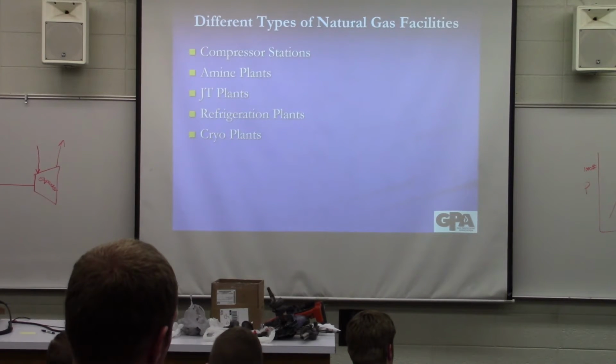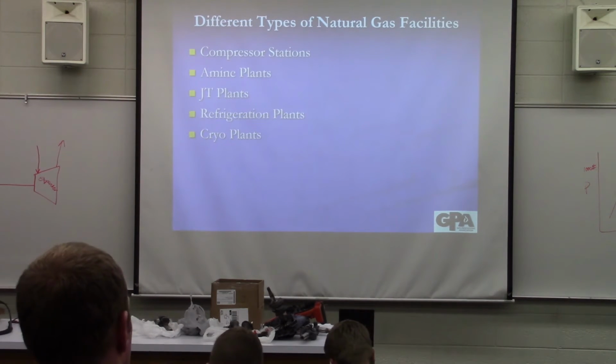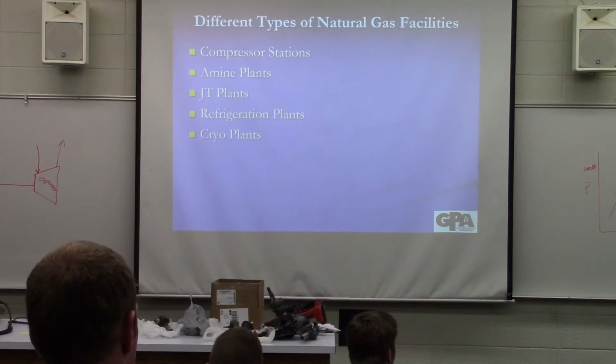As you start expanding, it expands into a gas. But right here, typically that's what you would expect: as you expand the liquid, it should become a gas. But here, there's a term for this. It's called retrograde condensation, right? So you go from a gas, and you actually do start to drop out liquid as you're doing an expansion, which is counterintuitive. That's not normally what you would expect.